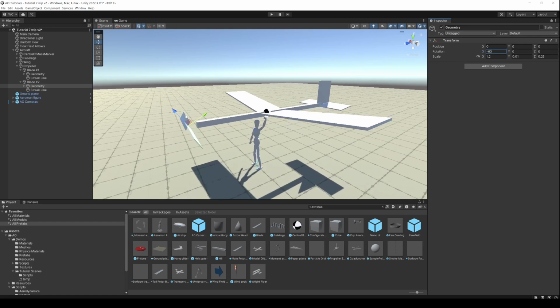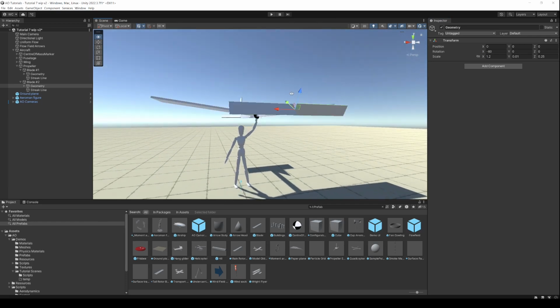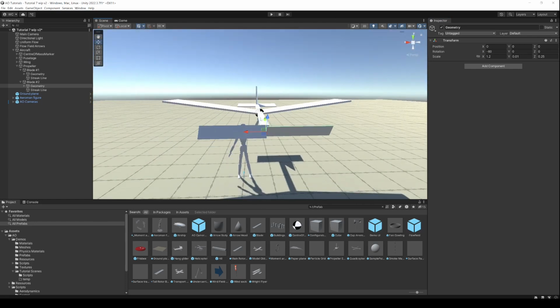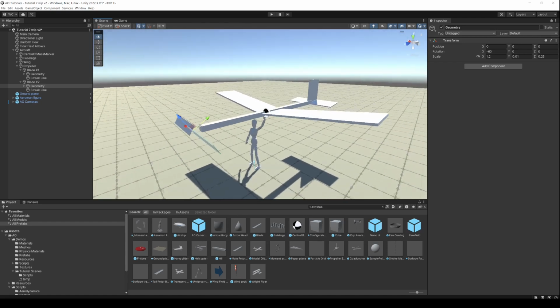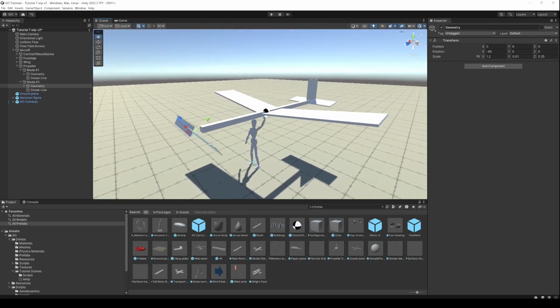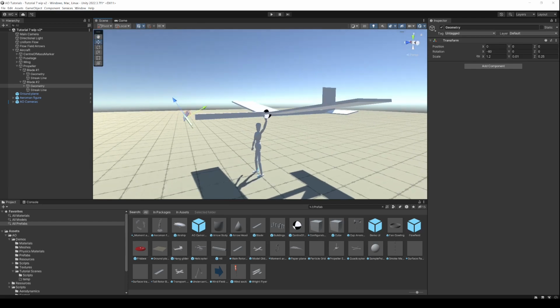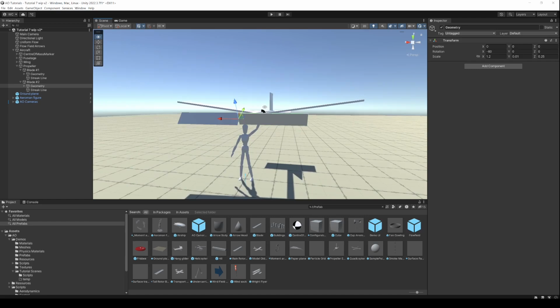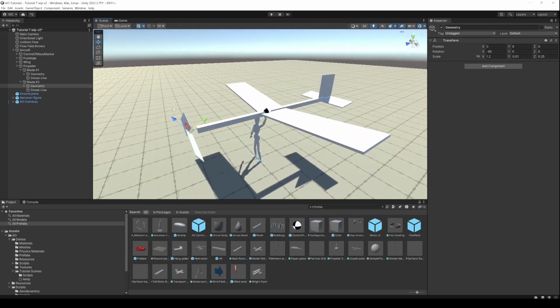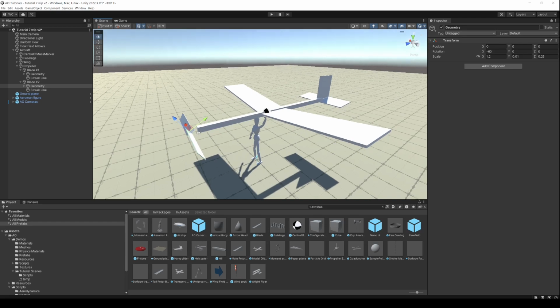There are only two things you really need to know about a propeller: its diameter and its pitch. Diameter, obviously, is the distance between the tips. The pitch is, if you imagine this is being screwed into cheese or something, how far the propeller would go in one rotation. It's related to the angle of the blades. If you want to go really fast, you need an aggressive pitch angle. But if you want to produce lots of thrust when you're not going fast, say when you're taking off, you want a more shallow pitch angle. So when you're tuning an aircraft propeller, you have to choose the pitch angle of the blades quite carefully, depending on the speed of rotation of the motor and how fast the plane is going.